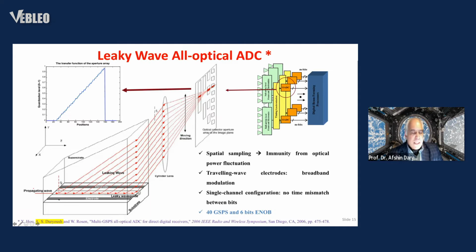The way that we accomplish that is using 2 parallel electrodes that are coupled microstrip lines, and then the optical energy travels between these 2 electrodes. If the velocity of light and the velocity of the RF signal are the same, by taking advantage of an appropriate substrate such as silicon, we would be able to have a very broad bandwidth capability. And as the optical energy travels, because of the superstrate with the higher index of refraction, it causes the energy to leak out.